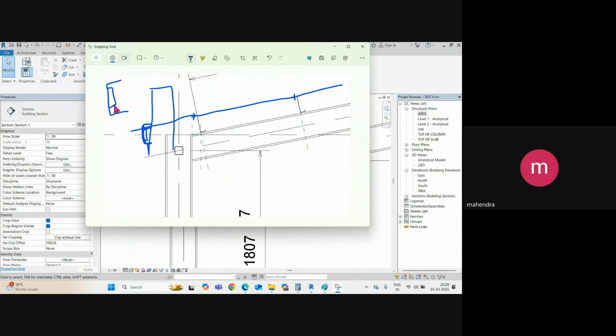Okay, and we need to add the angle welded to the plate. So you can use an angle like that, any 45 or 50, and this angle is welded to this column like that. So when this column is in fabrication, this angle is already welded to this column during erection. Okay, and then simply just bolting with this.